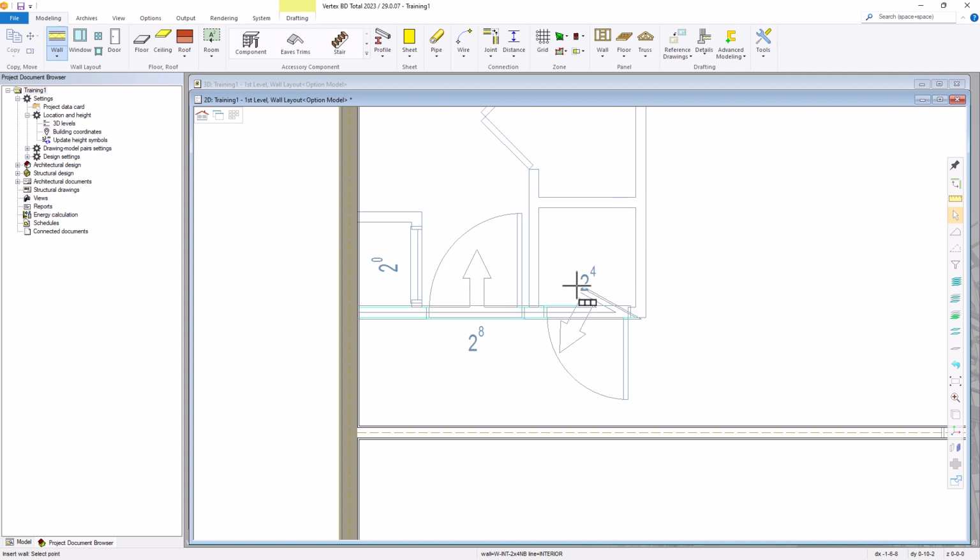You can't mirror, because then you're going to end up mirroring this wall off. So you want to make sure that you maintain the side, especially when you're turning the walls and turning corners, that you're still selecting the same exterior side and you're not flip-flopping between interior and exterior, or inside or outside, when you're making the turns. And Control Z one more time to undo that U key.